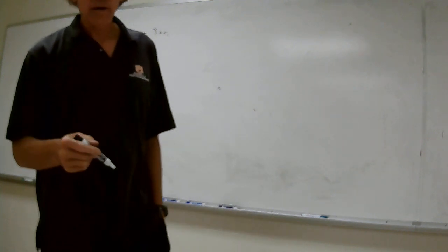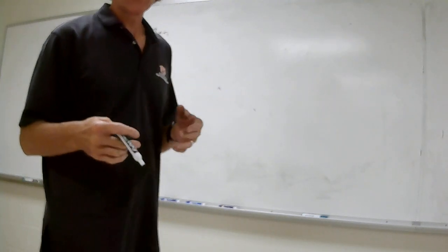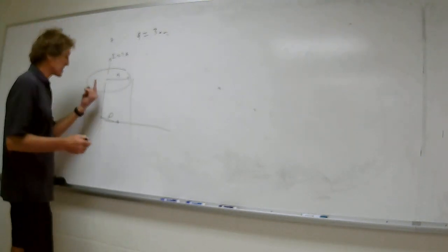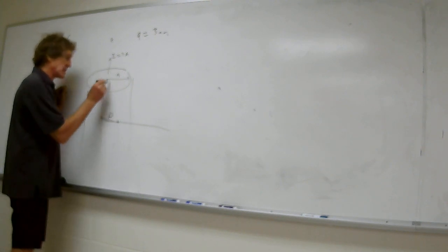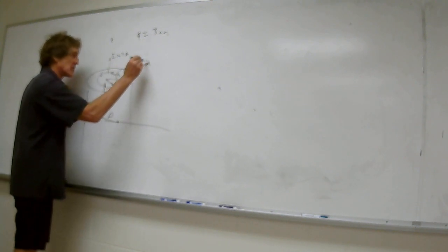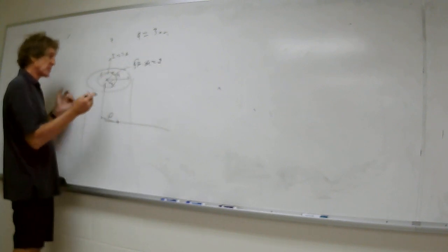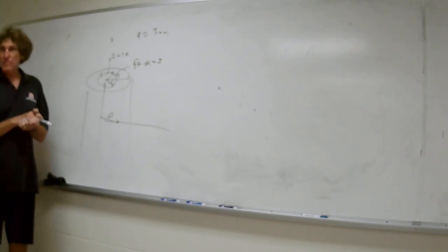That's fine. All right. For a problem like this, first you all agree it's a high degree of symmetry. If you look at this problem, all the currents go in that direction. And logically speaking, if you come out any distance rho and did that loop that I call the Amperian loop here, then the integral of H dot dl over that closed loop has to be the I that's penetrating the surface area of that loop inside it. Are you all with me?